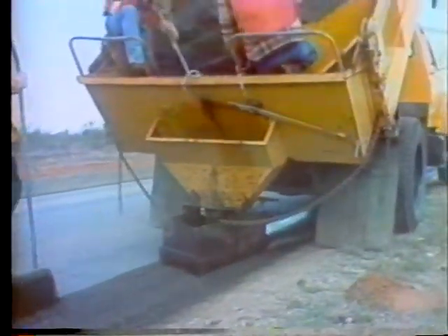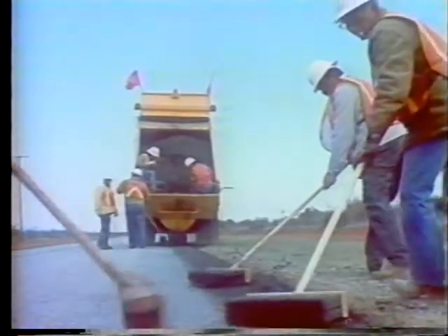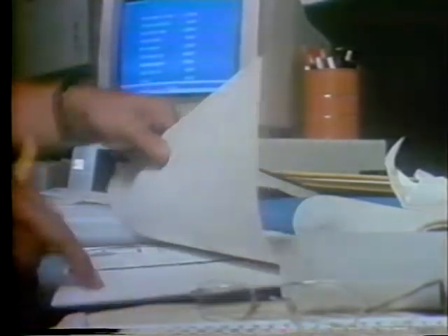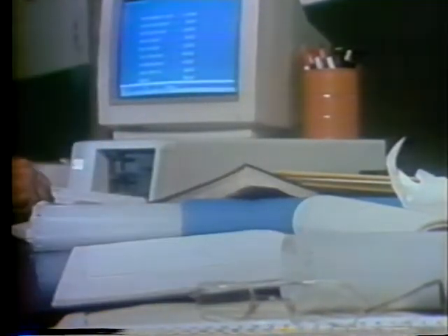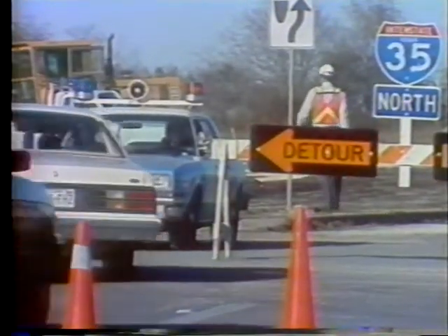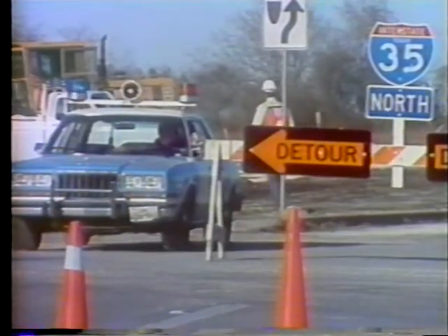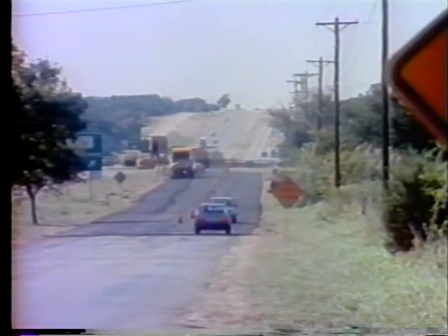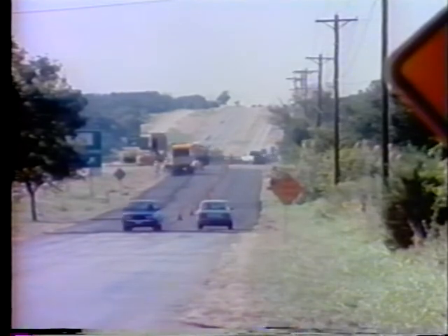When an edge drop-off occurs as a result of construction or maintenance operations, a plan to reduce the potentially hazardous drop-offs should be developed. This should be done prior to the start of operations. The plan should be strictly enforced during the actual construction work. This plan could include an item which requires the daily backfilling of the drop-off with a wedge of material on a 3-to-1 or flatter slope. Warning signs should be used in advance and throughout the treatment.